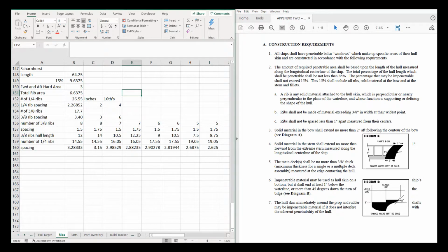What I did is take that calculation, this number right here, and convert it into something more useful. So inches is just the number of inches, and then I figured out the number of sixteenths to convert this number. You can see it's right near 0.25, so I expect it to be 4/16 or a 1/4. But if it's an odder number, it can be easier to see it in 16ths because that's what I'll actually measure.